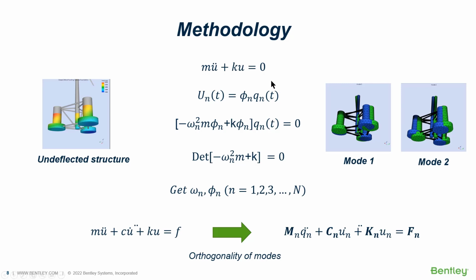Structural engineers use this undamped dynamic equation without external forces. And as we talked about right before, the engineers assume that displacement can be represented by assumed displacement and some time variant term. Displacement varies in time and space. They split this into a time and a spatial variant term here. Then after some operations, the solution of this equation becomes the determinant of this matrix.